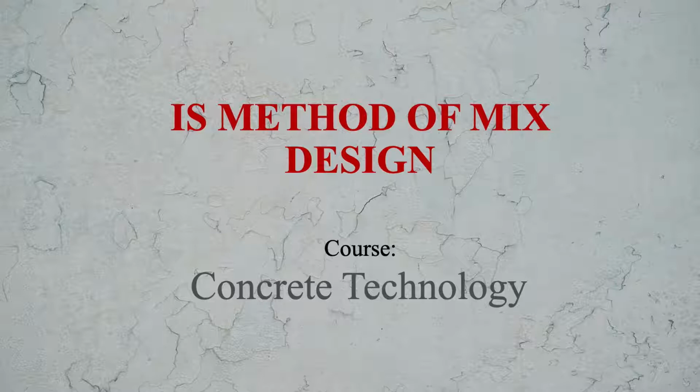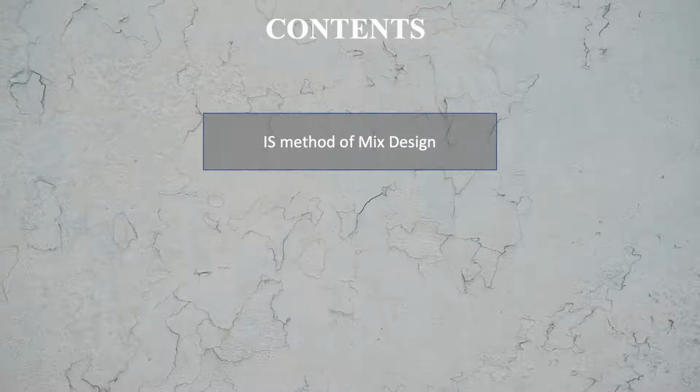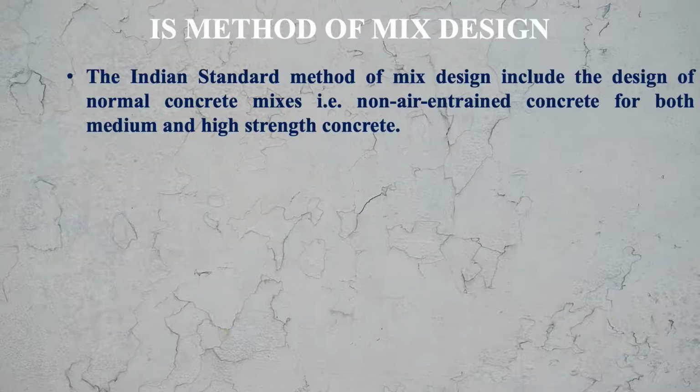Today I will discuss with you the IS code method of mix design. This method of mix design is given in the IS code. That is why we are calling it the IS code method of mix design. The Indian Standard method of mix design includes the design of normal concrete mixes, that is, non-air entrained concrete, for both medium and high strength concrete. So let us see what are the different steps of this method of mix design.